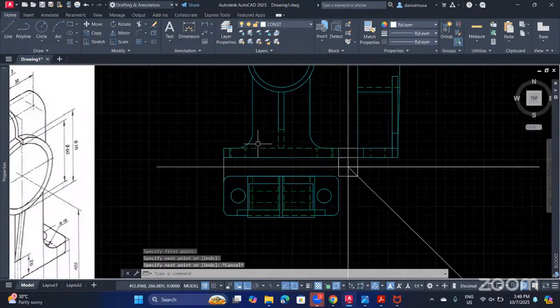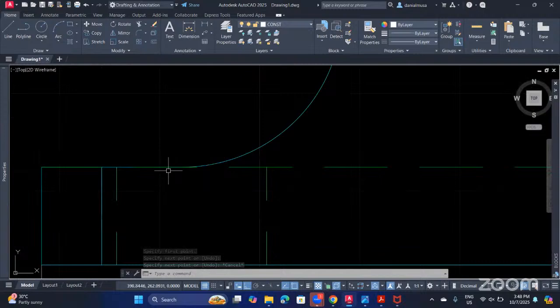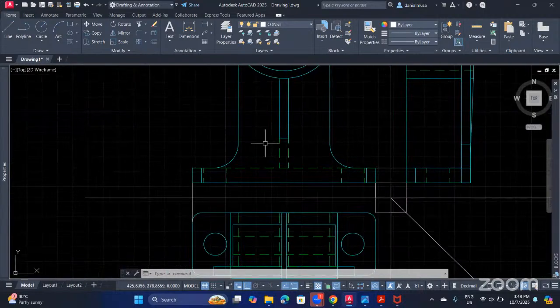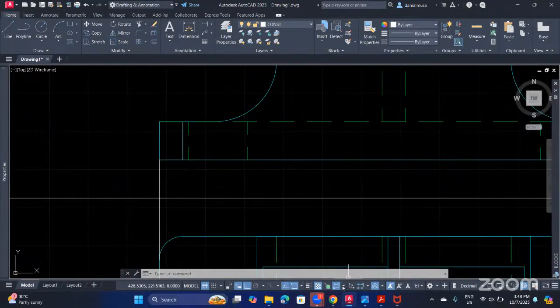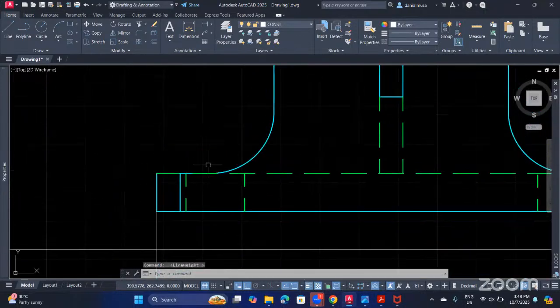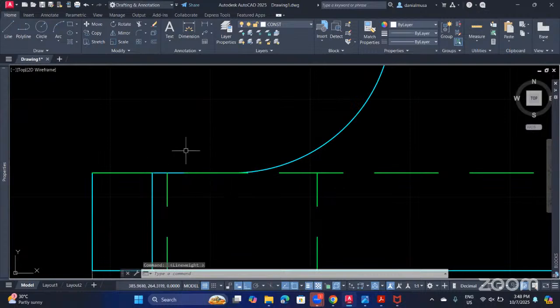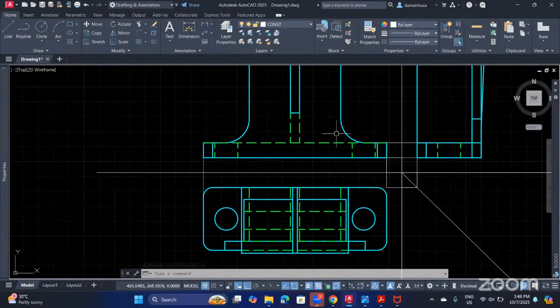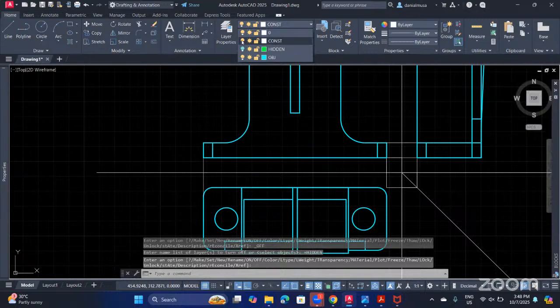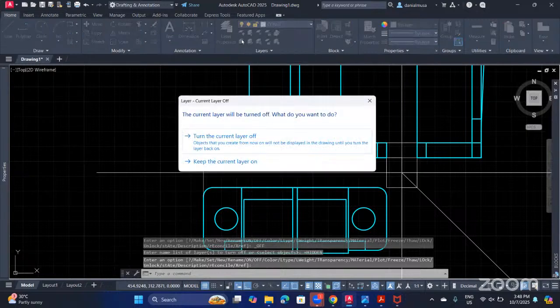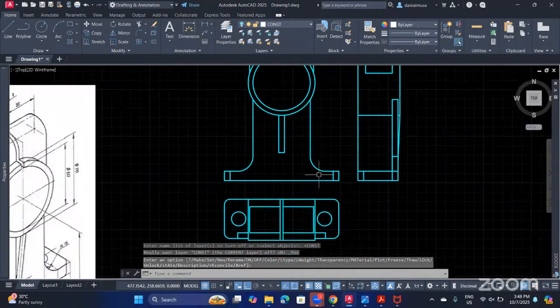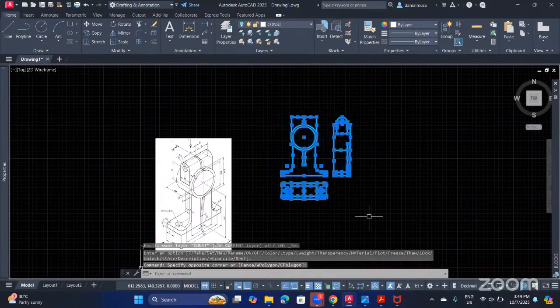Okay, but on the object, if you see here, the highlight line is on top of the object line. I think it's hard to see, so I just open it. Yes, the header is on top of the object line. If you don't want that, one way is like this. You can close the heading line and the construction line here, just turn it off. Right? So you just cover it.